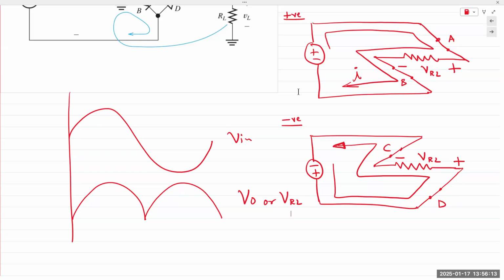And that high frequency signal, high frequency compared to the power outlet, then requires a much smaller transformer instead of a 110 volt transformer. The size of the transformer is now far reduced, very, very small. And so that small transformer reduces the weight of your adapter. That's why those adapters are very lightweight.